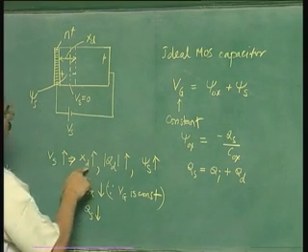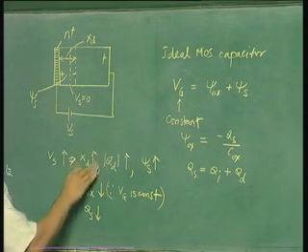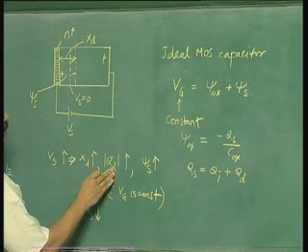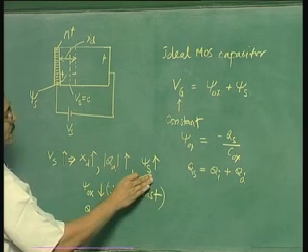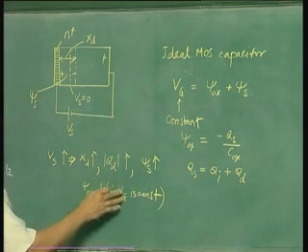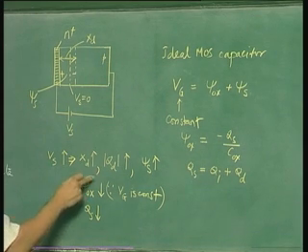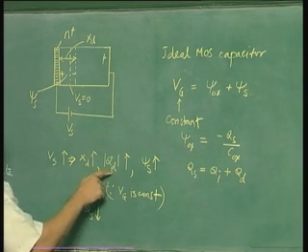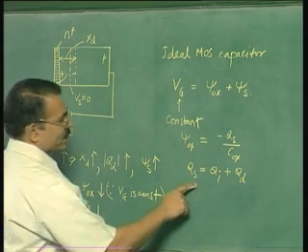So please note that we are proceeding in this order, okay, in a logical fashion. First you start with increase in the depletion width, and then logically this means Qd increases in magnitude. This also means psi s increases in magnitude, and since Vg is constant, it means psi ox decreases in magnitude, and psi ox decreasing in magnitude means Qs decreasing in magnitude. Now Qd magnitude is increasing and Qs is decreasing. Look at this equation.